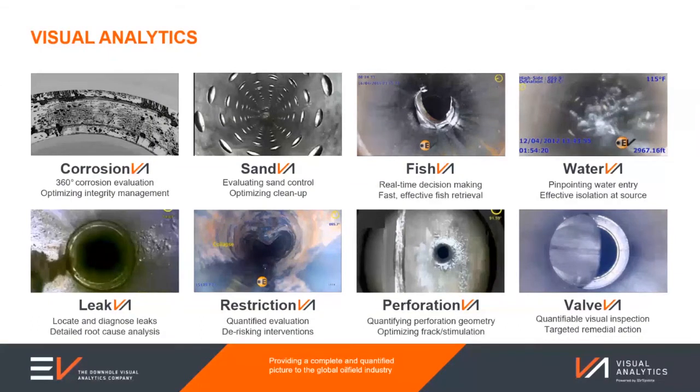Ernesto, thank you. Those are two excellent questions, and I'll take them each in turn. Yes, we do have a number of examples where we've been in and investigated hydrate formations and the issues that they bring. I do have a little clip that's buried in here somewhere, but it's probably not right to show it. Again, with the video, you can see quite clearly where the hydrates have formed. We've even been involved in operations where the operator's gone in with MEG or a similar solvent solution. They've circulated it around, perhaps with jointed pipe or coiled tubing on top of the area of interest, and we've popped in and out to have a look at the progress and how that's been eroded. I can think of a number of cases in West Africa where we did that in subsea wells, to great effect, helping to remove that problem and manage the symptoms there.